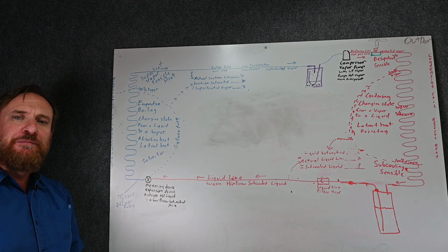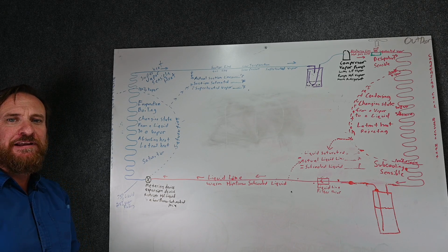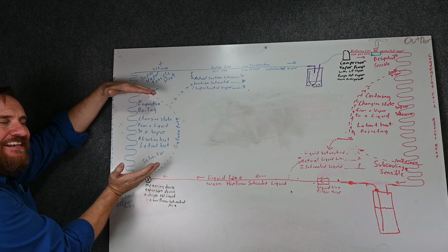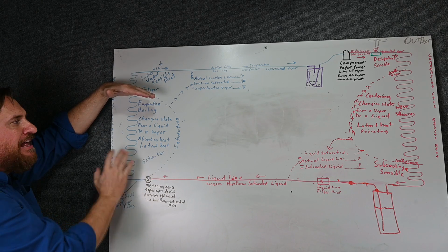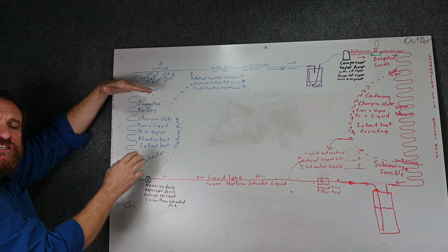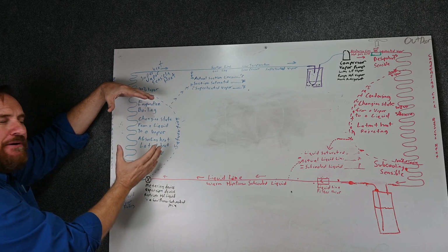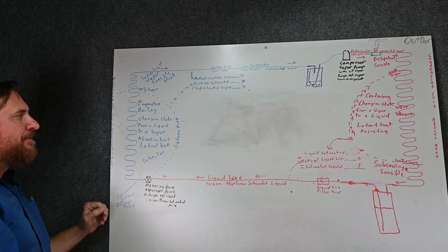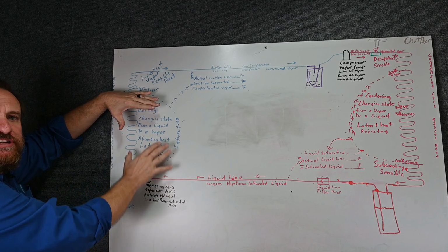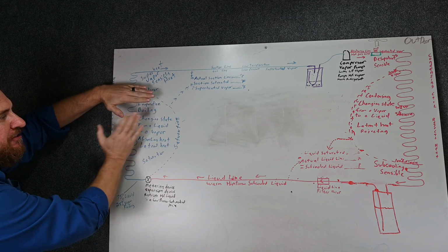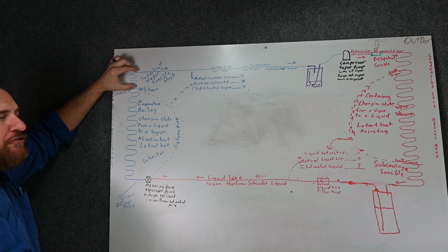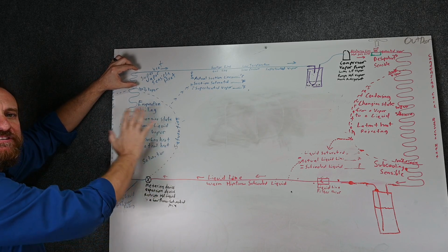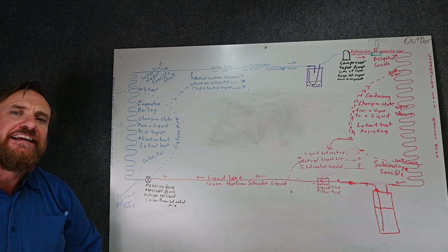Then we moved over to a thermostatic expansion valve and an electronic expansion valve. Those valves simplified things because they maintained a steady state of liquid refrigerant in that evaporator coil. They maintained a set amount of saturation, that refrigerant boiling from liquid to vapor. It had a valve that opened and closed, so the outdoor temperature didn't have nearly the effect on it. It couldn't measure how much saturation is taking place, but if we knew we wanted this much saturation, it could measure this much superheat. And if I maintained this much superheat, I know that I have this much saturation. So those valves simplified things a lot.